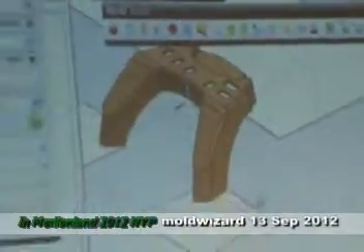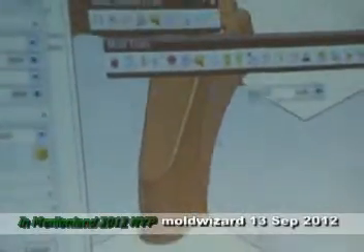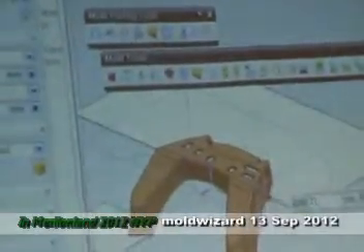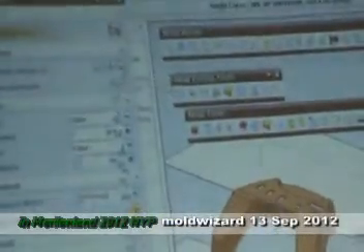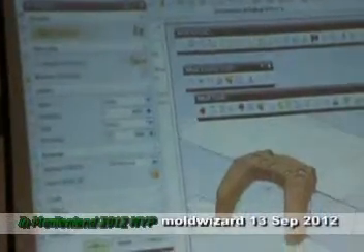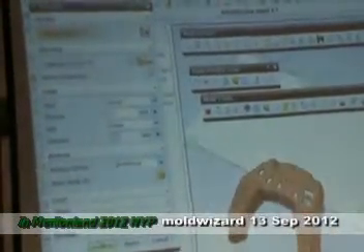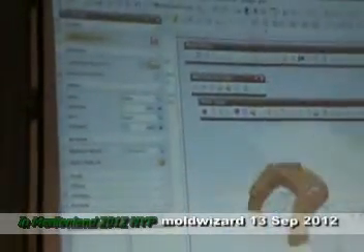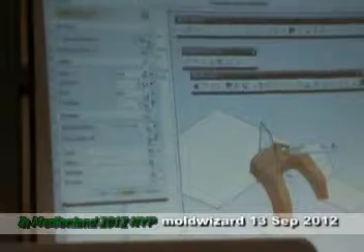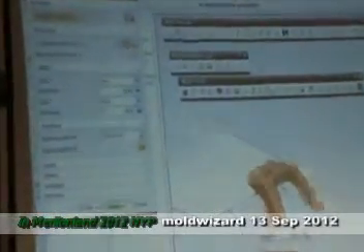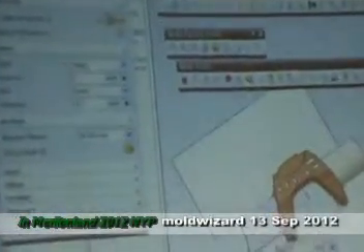We'll go to extrude and then select this edge and define the vector. This vector will be y, and select them. This time should be perfect. Apply. And this time for this one, the direction will be negative y. Apply.